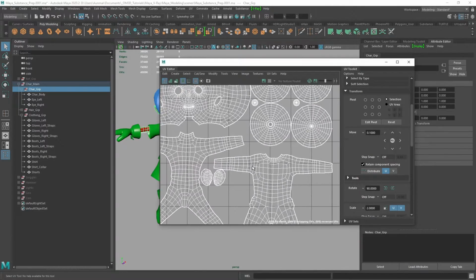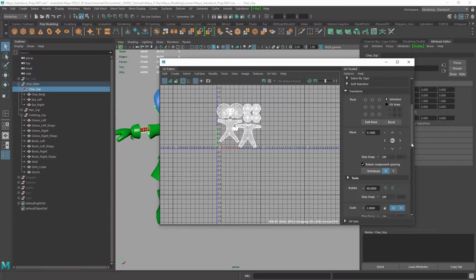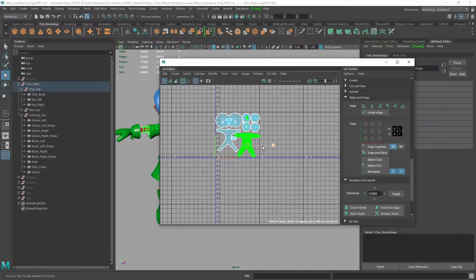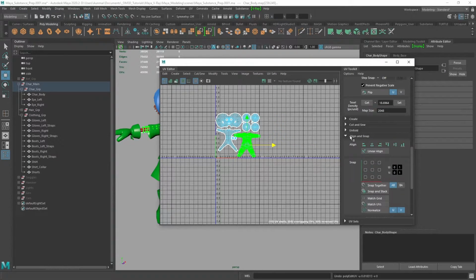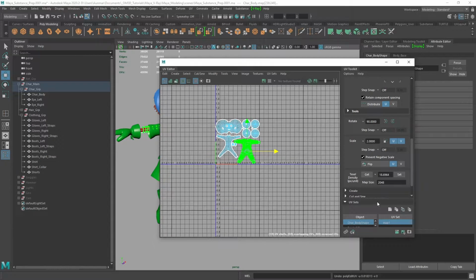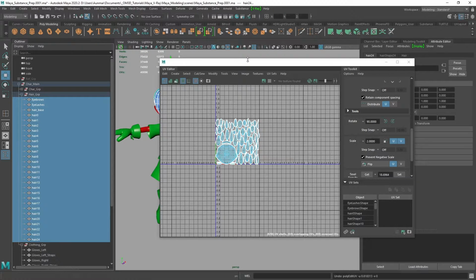There's no overlapping UVs. There's no floating UVs. In this tutorial, we will not be using what's called UDIMs, so we won't be using any textures that are on the next coordinate system, okay? So with that in mind, you do want to check your UV sets and make sure that you only have one map here, okay? You may not be sure why, but that's essentially the UV channel. And since we're not using UDIMs, we don't really care about that right now.